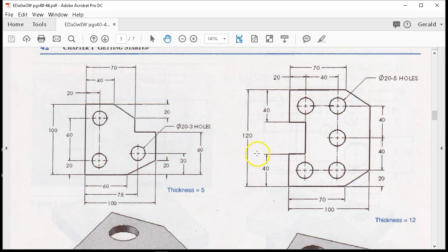All right, 1-8 has notch, and this would really be the first introduction to a linear pattern. And one of the things with the linear sketch pattern, or using it in two directions, becomes like an array, is that this middle circle that's missing, I'm going to go ahead and leave it. I'm going to make it construction geometry rather than disrupt the pattern.